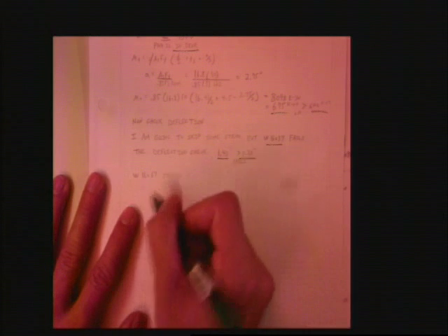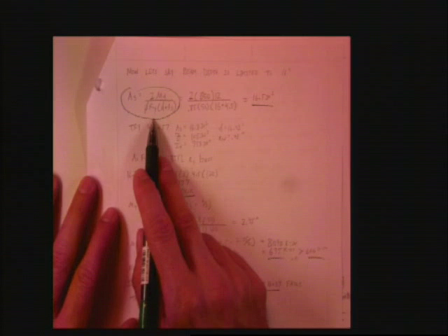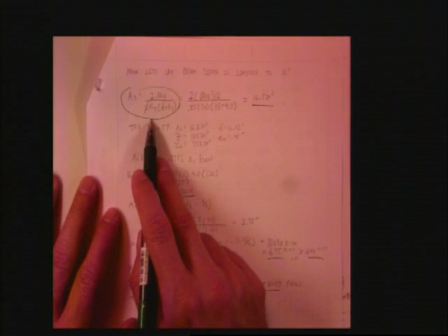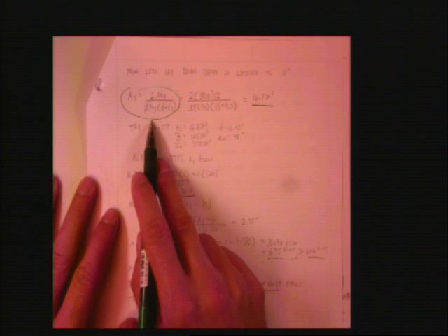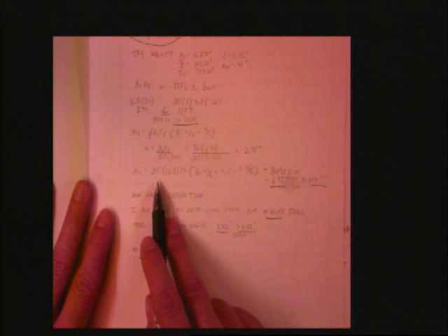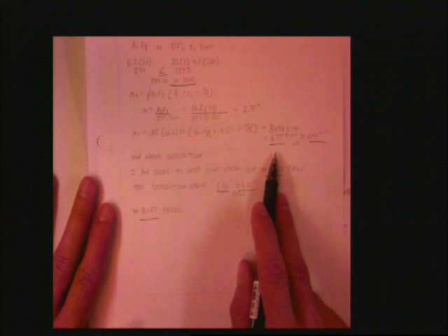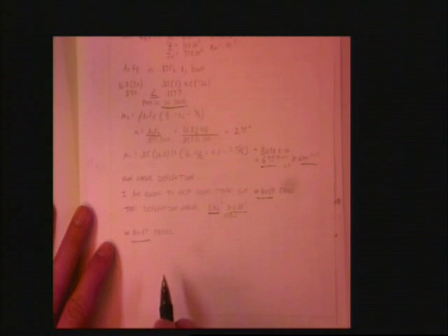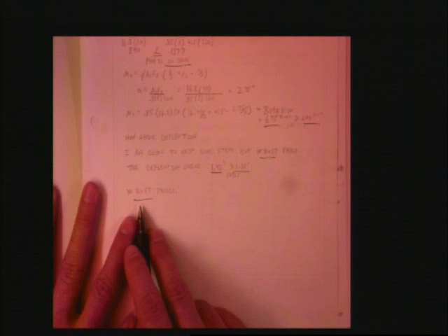Okay? So that means you have to upsize. So let's realize that when we do this simplified calculation, that's only for stress. Okay? That's only a strength check. And even though we do it, we cannot assume that that is going to provide the right answer. We have to check it. Okay? But we're going in with a very, very good guess. And that's what you want for design purposes. Start out with a very, very good guess. Okay? And it actually worked for strength. But when it came to deflection, it didn't work, and we needed to increase the size a little bit. So from a W16 by 57 to a W16 by 67. Ended up working. 10 more pounds. Oh no.